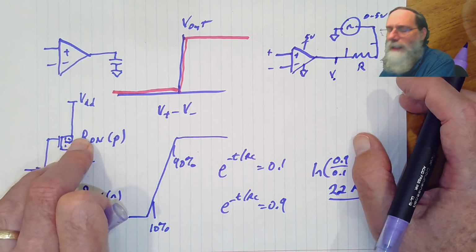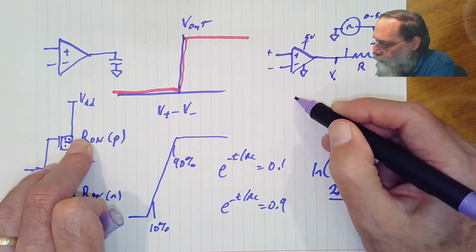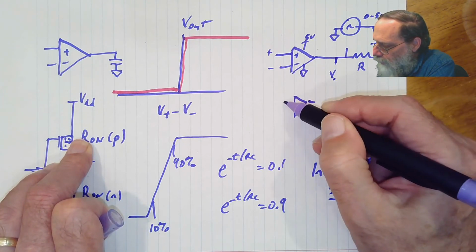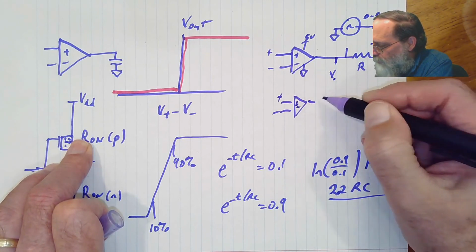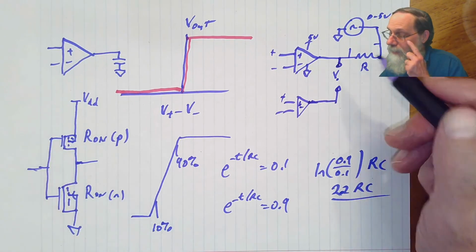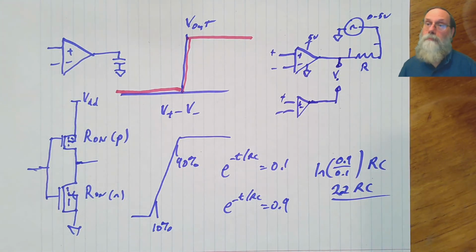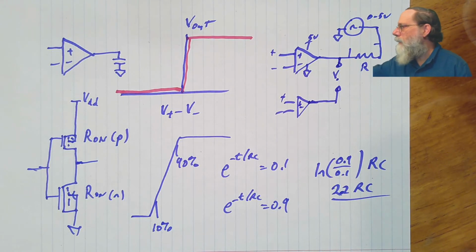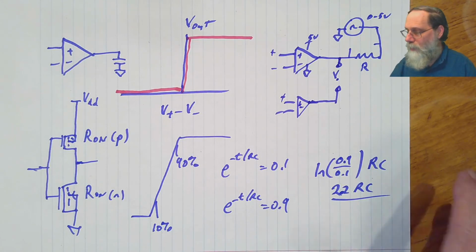If we want to be a little more careful, if we're not sure that this thing is going to go all the way to the power rail, we can do another one hooked up to the same plus and minus inputs, and look at the voltage difference between the loaded and the unloaded circuit to figure out how much the voltage has changed as a result of this load. It's easy enough to set that up and measure it with the Analog Discovery 2.